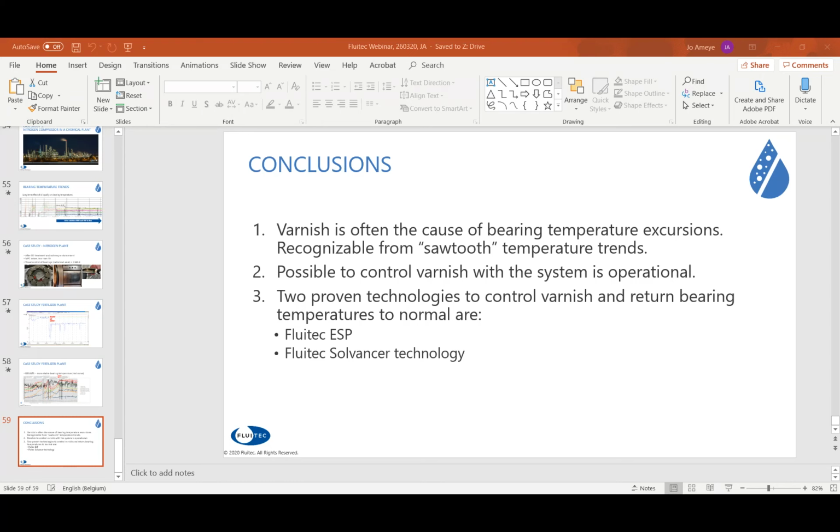So your first question was on mixing oils, was that the question? The effect between a lubricant oil or the hydraulic oil with the solvent cell? With hydraulic oil, of course, you don't have the high amount of circulation. That is the only issue: you need to make sure the solvent has a chance to work. You don't have the same flow rates as on the lube oil. That's the only thing you have to watch if you want the solvent to act and work. But in any case, it will work as well on hydraulics as on lubricants.